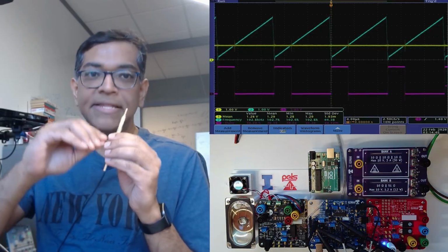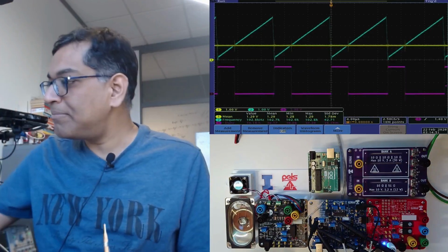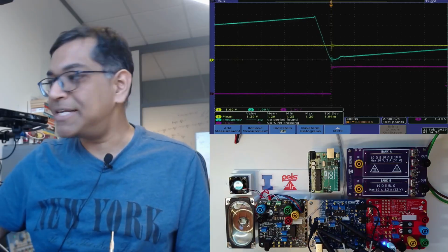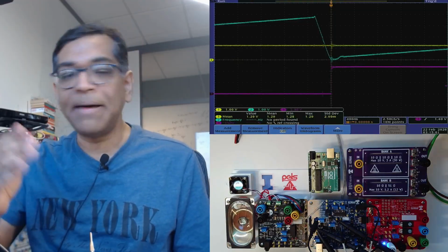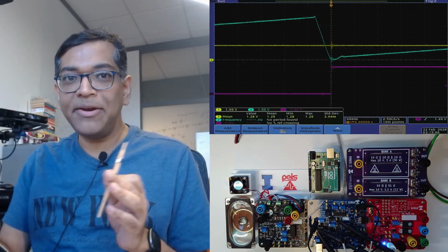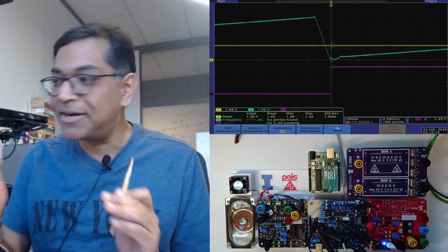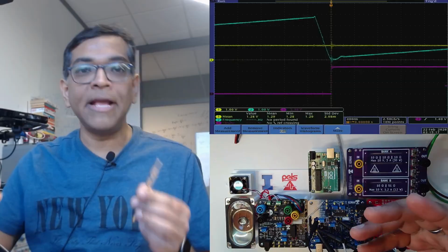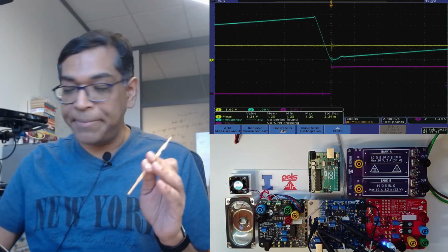because the ramp is going up and then there is a fall. When you are looking at a large time scale it's fine, but there is a finite time during which it's not exactly a sawtooth, but has some kind of falling edge. So you have to be careful when these things become trickier. If I am trying to push my switching frequency even higher, I need to be careful about what this discharge time is, and I need to pick my components such that this becomes a minuscule part compared to my overall time period.